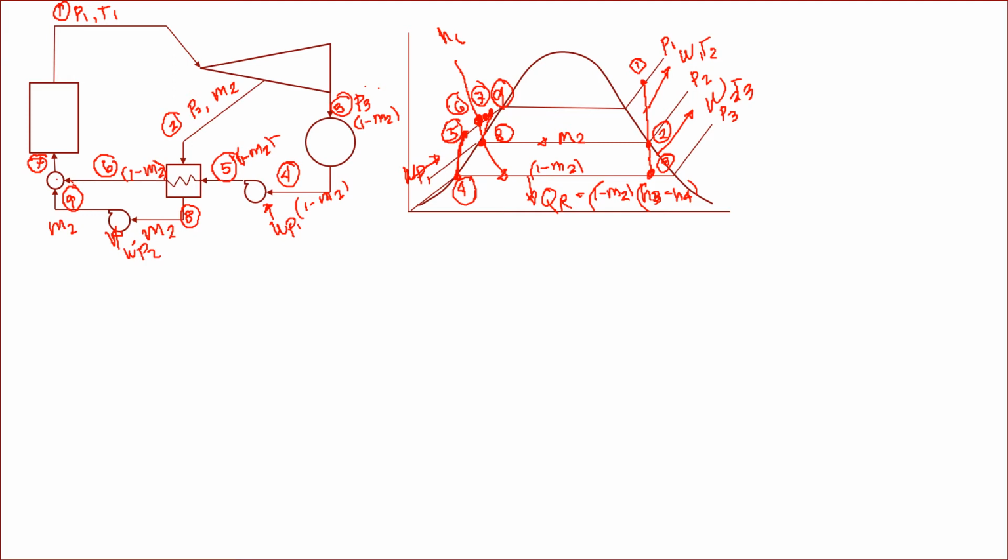Okay? So there is a heat addition wherein QA now is equal to H1 minus H7. Okay? And there is also a work of the pump here, pump 2. Okay? So we want to determine the enthalpies of that. We want to solve. So there is the point 1, pressure 1, T1. We can solve H1, S1. At point 2, pressure 2, with the assumption of isentropic process, S1 is equal to S2.